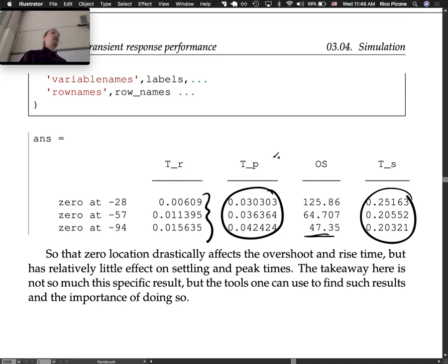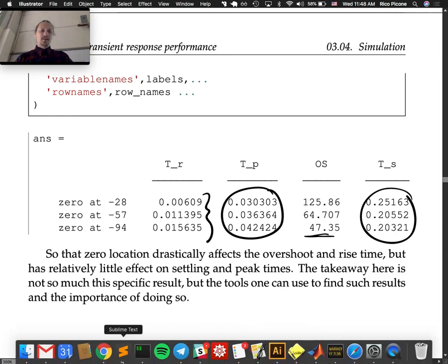So, anyways, these functions, like tf, lsim, and stepinfo, were the 3 main functions that we learned about in this lecture, and they're vastly helpful for doing design of a control system in MATLAB. We'll expand on that. Next week we're going to be digging quite a bit deeper into how moving things around in the S-plane affects these parameters. So, all right. See you on Friday.